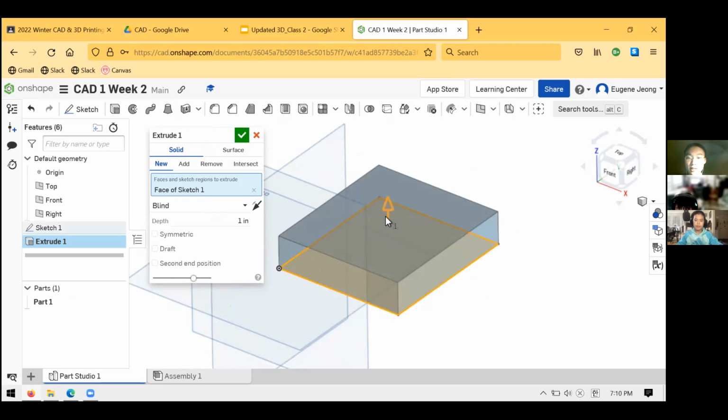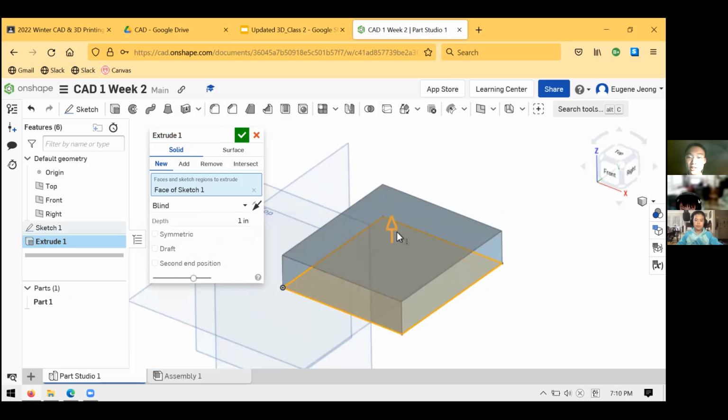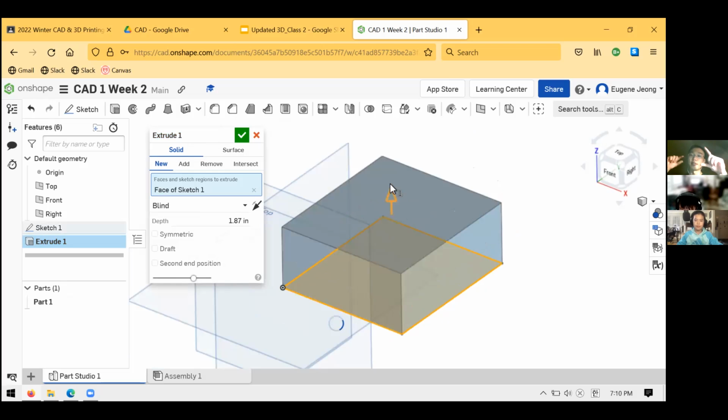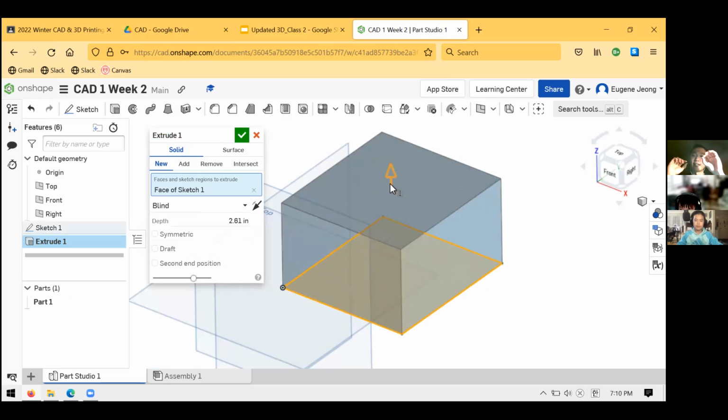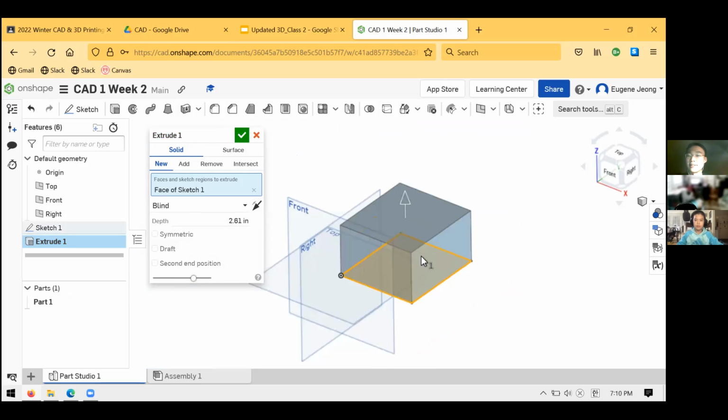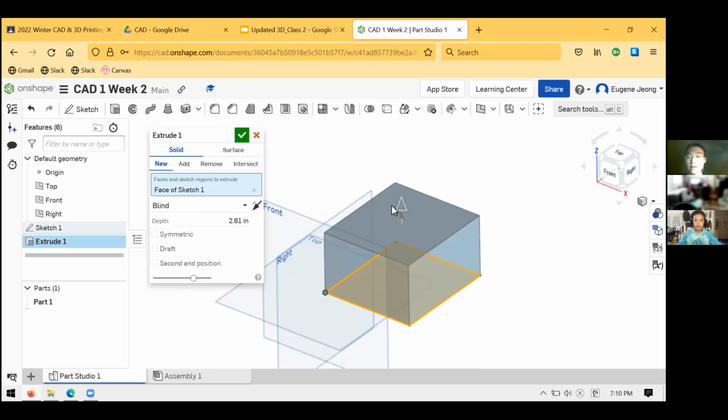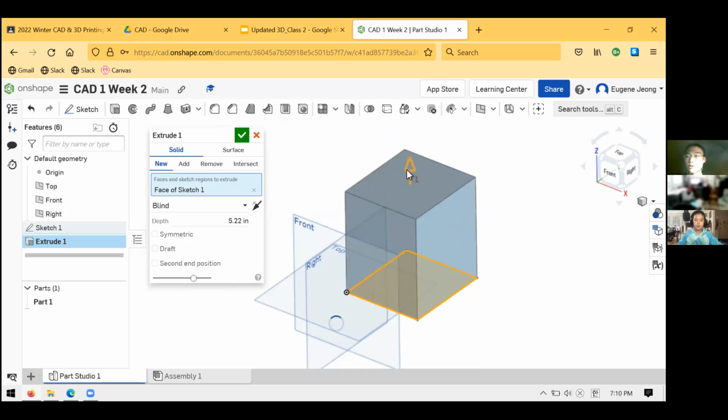And you can kind of see what I mean by extruding, right? Maybe you've played with those Play-Doh toys before, where you have a little shaped mold, like maybe a heart-shaped mold, and you push the Play-Doh through the mold, and it comes out in a long rod of that shape. So that's all we're doing right now. We're taking our sketched shape and we're extending the material. We're pushing it through that shape to create a solid object.